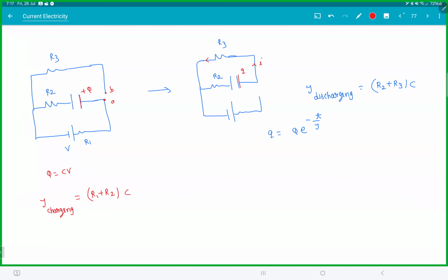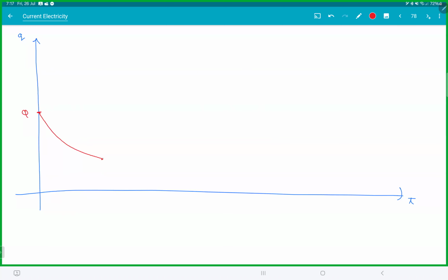Right? So how will that circuit look? If you flip it back, now you start charging. Now the equation would be slightly different, but we know definitely it will be charging. But think of it like this. If you just leave it for a long time, what will happen? You will try to reach here. Won't it again start charging up? Is that making sense? And then again you flip the switch. But remember, to reach the same value of Q again, it will take infinite time. To completely discharge will take infinite time, and to go back to Q will also take infinite time. So this will increase, but by that time t is already over.